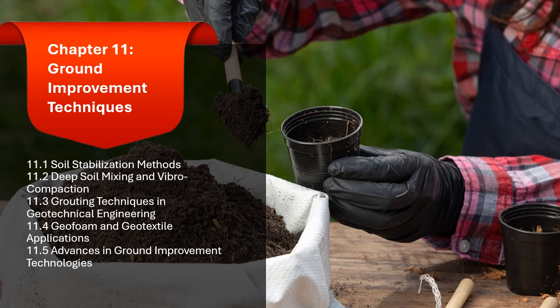In earthquake-prone areas, geofoam helps reduce the impact of seismic forces on structures by minimizing ground shaking and settling, providing a flexible solution for infrastructure projects in such regions. 5. Foundation support. Geofoam can be used as a lightweight, low-settlement material for foundation support, especially in areas where conventional fill materials would lead to excessive settlement.